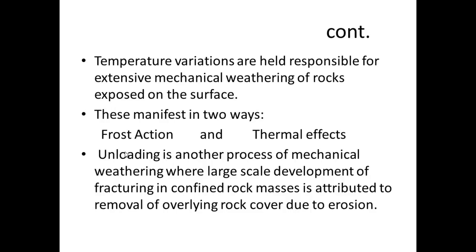There's another process which is known as unloading. Unloading may be defined as follows: due to the prolonged erosional work of the natural agencies, the overlying rock cover gets removed, because of which the rocks expand upwards but remain confined from the sides. When the erosional work is performed by these agencies, the top layer of these rocks is removed. These rocks, although they remain confined from the sides, expand upwards.